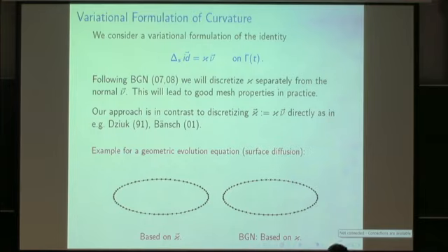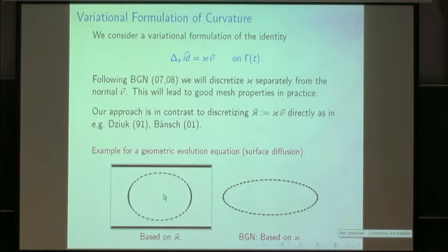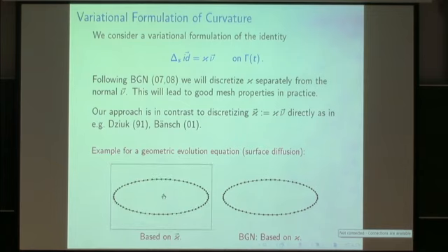And the downside is that then you've got no freedom in the tangential direction. So that means the vertices are basically all moved in the normal direction, and you can see what happens. You get a high clustering of vertices at these two ends, and if you take that to an extreme, eventually you will not be able to solve your system of equations at each time step anymore, because your system is so ill-conditioned or actually becomes singular.